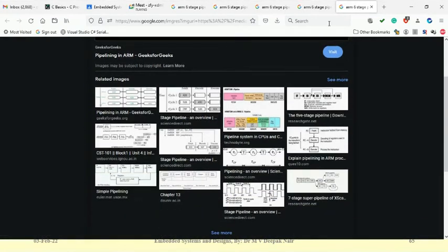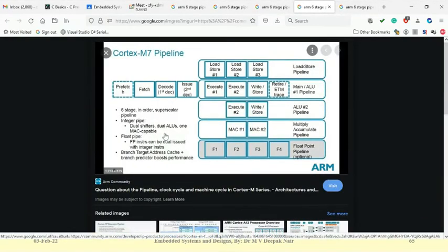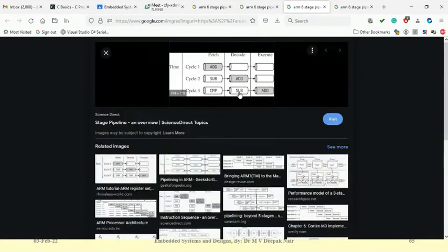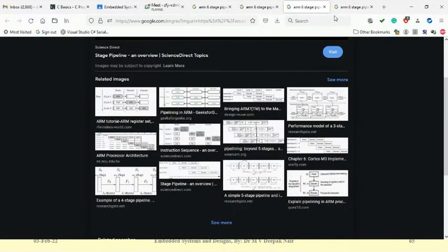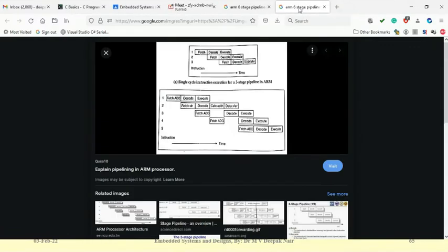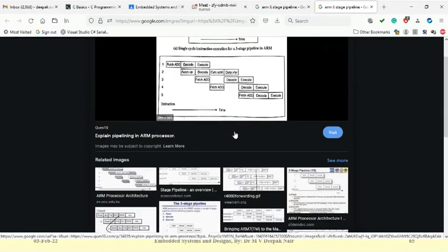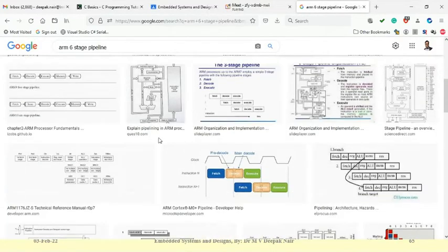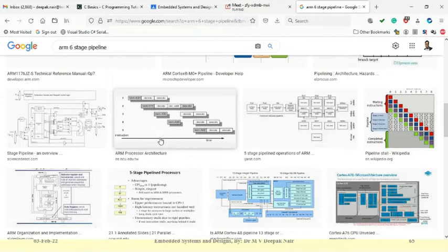We don't have to look into that part because we are going to use ARM Cortex M4. So M4 uses a 3-stage pipeline. You can go and check what other blocks are introduced when you go for a 6-stage pipeline. I had that image with me, but I think I have not put that in the presentation.